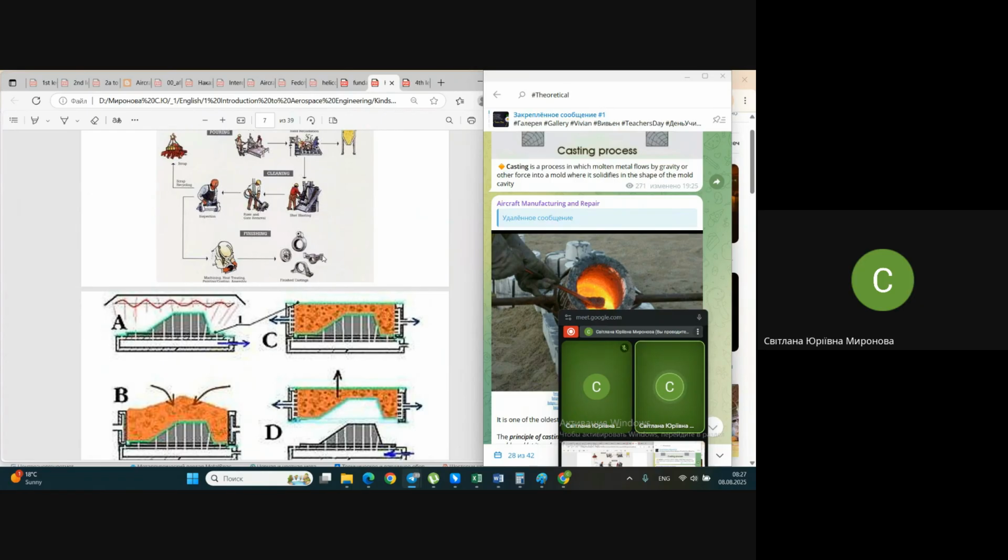I'm not talking about some overburned surface or something like this. If everything is clean, it might still result in a different surface finish, the roughness, these peaks and valleys on the surface of metal, which may be of different values. And we need to understand that different processes may result in different quality.